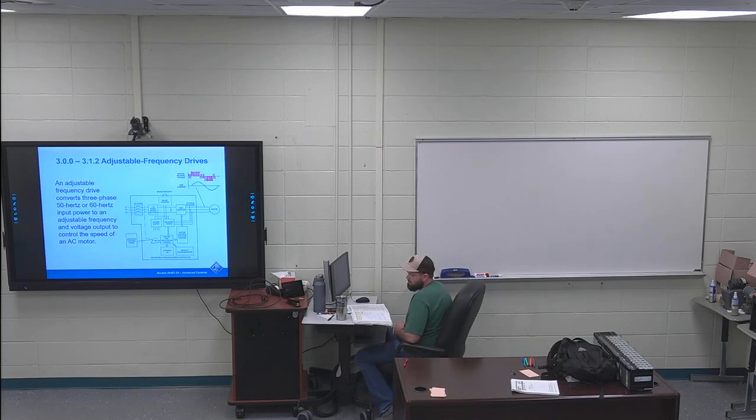What I have highlighted is the speed range at constant torque. So your speed can change, but you're going to have constant torque throughout. You're going to use it from 0 to 100%. You're going to use the feedback vector. So vectors are what you're going to use in this, but the feedback vector is what you're going to use for constant torque throughout a 0 to 100 speed range.